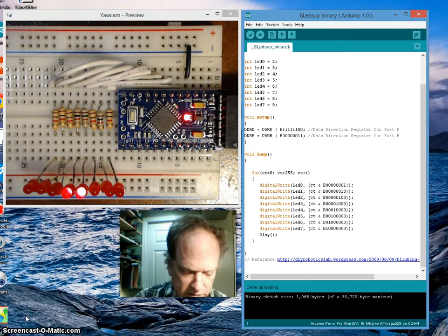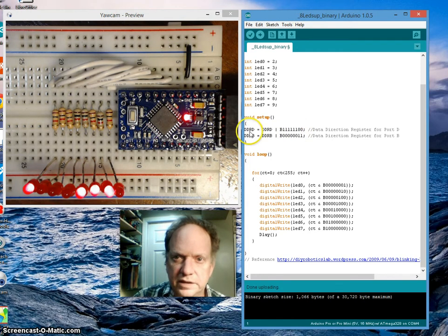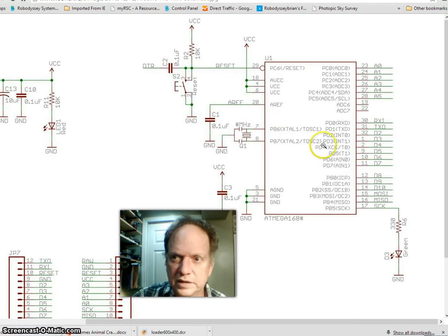What I wanted to do is touch a little bit more upon this point about looking at the code here, the data direction register. Recall ever so briefly that I said if I wanted 8 LEDs from the last video, that I need to steal 2 of them from port B, okay? Because 2 of the ones from port D are set for transmit and receive serial signals, and they're kind of committed to that. So it's just as easy to go ahead and steal 2 from B.